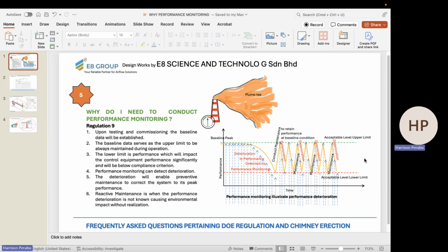Now, for an absorption filter, what is an absorption filter? An absorption filter, which is most of the time constructed of activated carbon, is to remove VOC, volatile gases, and certain types of acid and what's not, which is primarily for VOC. So these filters are to tackle vapors or contaminants in gaseous form. These air cleaning devices are not made to remove aerosols or particulate matter.